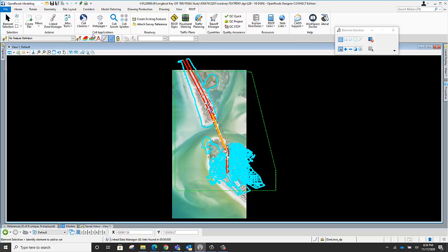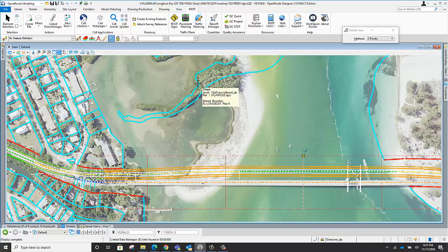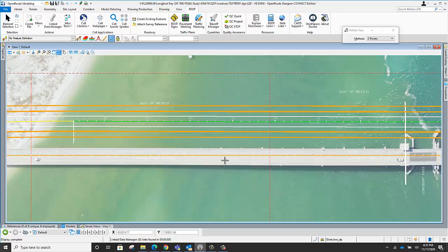So now to orient our view, just straight MicroStation, rotate view, my 2 points. We'll use those borders from the plan label to help orient our view so everything is right side up when we do our sheet printing. And I'll zoom into one of these sheets and let's just do something straightforward like a station offset. That requires us to select an element so we can read it. It reads an intelligent element such as the alignment and gives us our station and offset values.